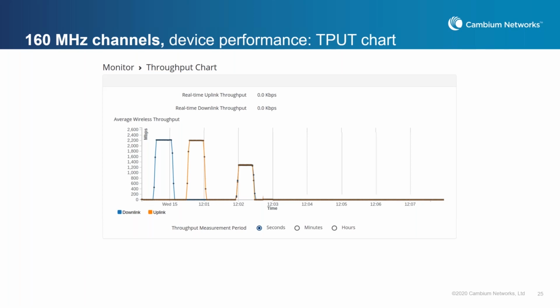So if we calculate the worst case scenario with the 120 stations and go into an 85-15 ratio, we will just not have enough time to send the uplink acknowledgements in a reasonable time. The latency will go through the roof. So that's the main reason why we're not going into an 85-15 ratio.